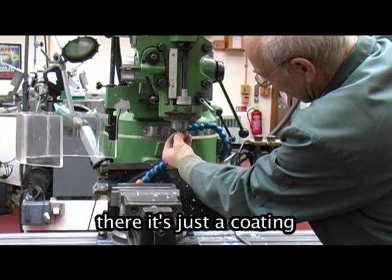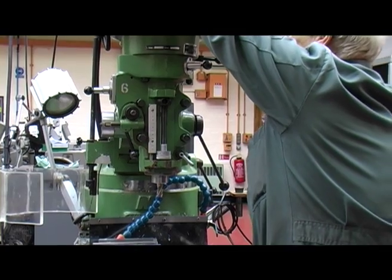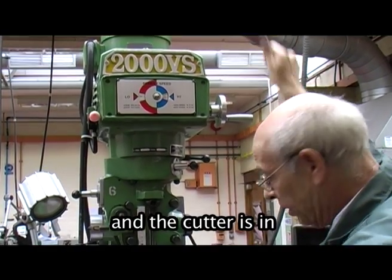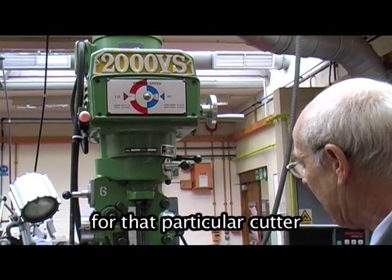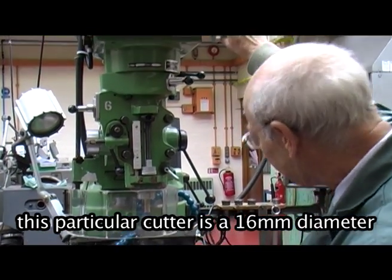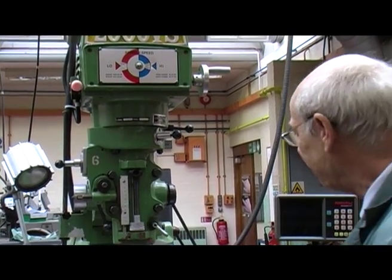Push the cutter up to the golden colour there, it's just a coating on it, gives you an idea of how far to put the cutter in. And the cutter's in, ready to go. All we would then have to do is adjust the speed to that particular cutter. This particular cutter is a 16mm diameter, so this needs to run at about 625. So that's the speed for that particular cutter.